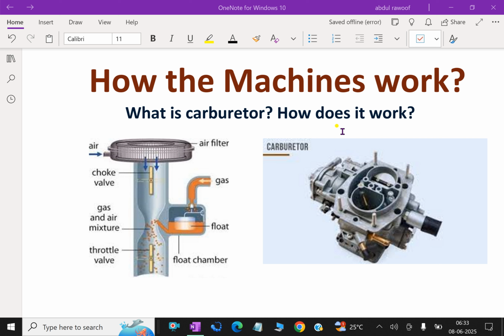The primary function of a carburetor is to mix air and fuel and make a combustible mixture. A carburetor is responsible for engine speed. It controls the proportion of air and fuel in different mixtures for different engine situations. It keeps a certain amount of fuel always floating in a chamber. It controls the ratio of air and fuel. It vaporizes the oil or gasoline to make a homogeneous mixture of air and fuel.